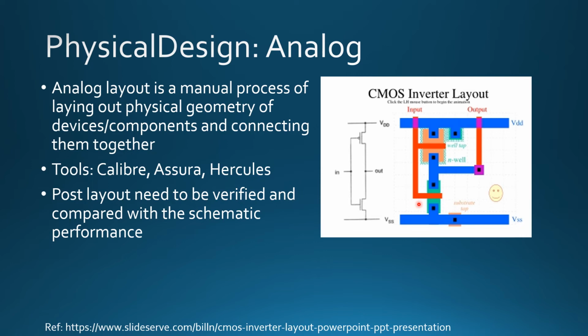Then what we need to do is only connect those gates together, connect the drain and source of the NMOS and PMOS together, and take the output. The same way, we can implement all circuits, bigger circuits as well. So that's the main idea of laying out.